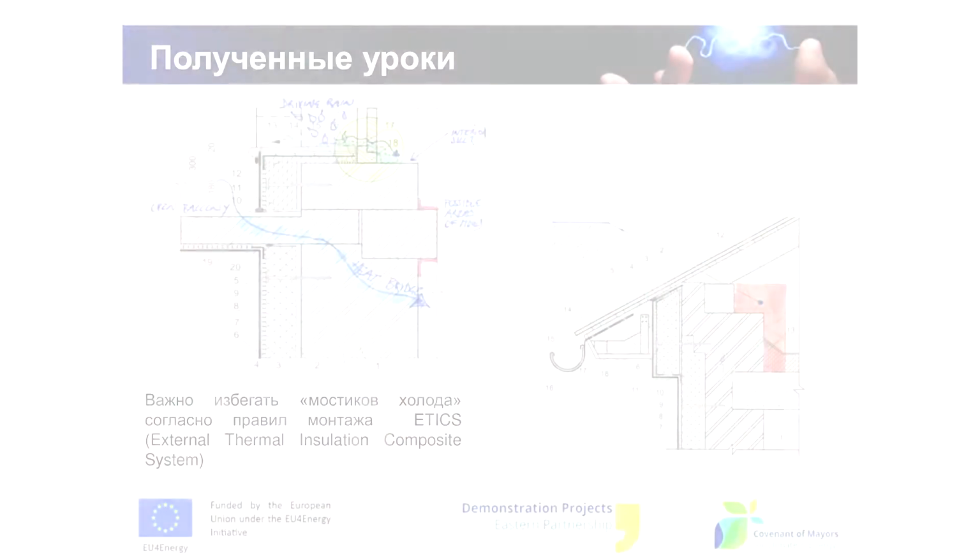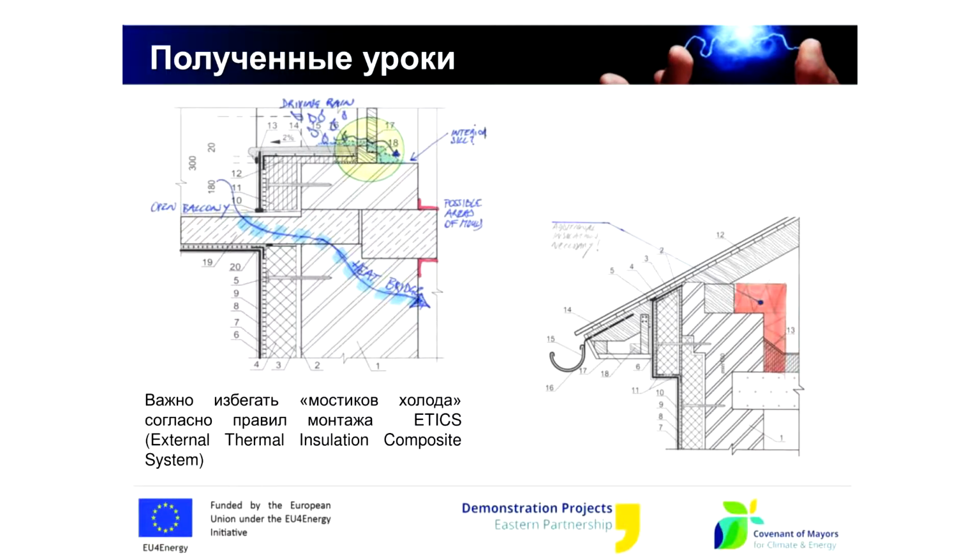When we talk about thermal refurbishment of buildings, it's necessary to analyze the documents regarding the presence of the cold bridge. We talk about the pencil rule when we talk about insulation. And if, for instance, you have forgotten the balcony, this concrete plate will accumulate cold.